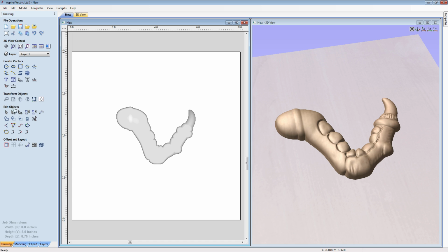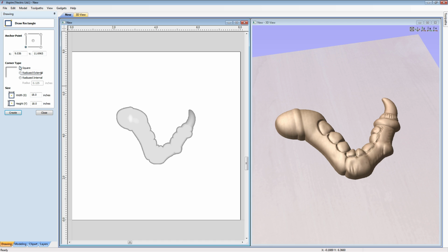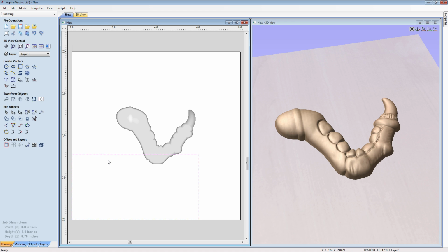First, I'm going to come to the Drawing tab. I'm going to create a rectangle, and for the outside of our mold we're going to make the part 6 by 3 1/8, and we'll just put that at x0, y0 and hit create, close, select that and hit F9 to center it. So that looks like a reasonable size. The part will be sat in the middle there.